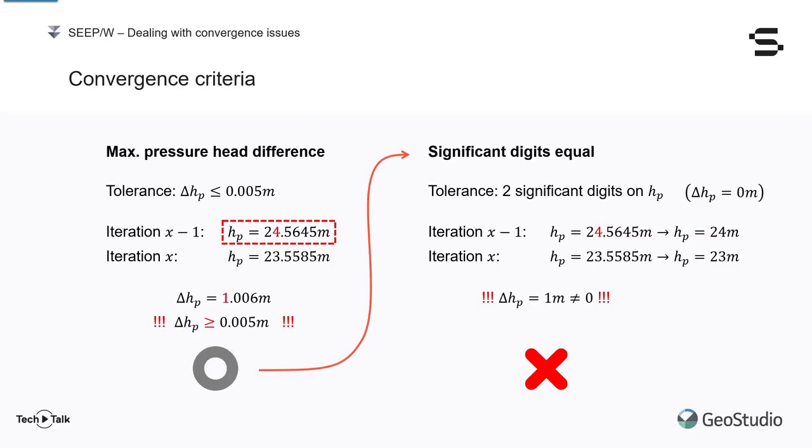As you can see, a red X indicates a worse convergence issue than a gray O. While gray O's normally indicate light convergence instability between iterations, red X's really require your attention as they indicate the answer is changing profoundly between iterations.